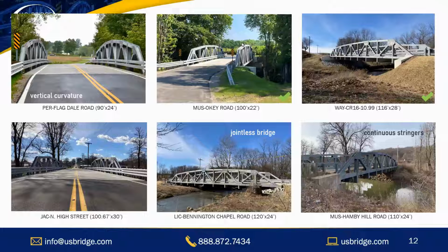Similarly, the lower center bridge, Bennington Chapel Road, features a jointless end of the deck construction as it transitions to the approach slabs. We used a deck extension that extended up past the end stringers over a stubby little back wall and cantilevered behind it and married up to the approach slab, which pushes the cold joint beyond the back wall.